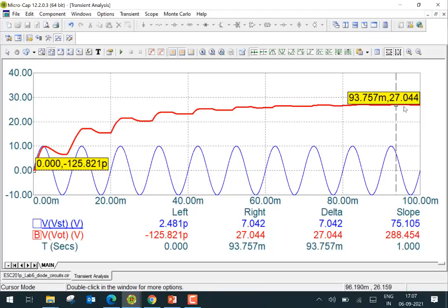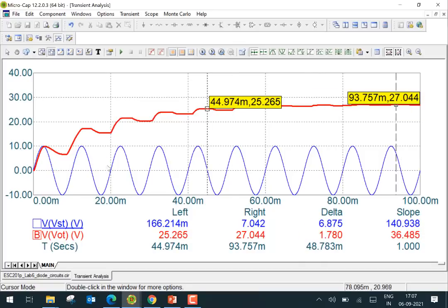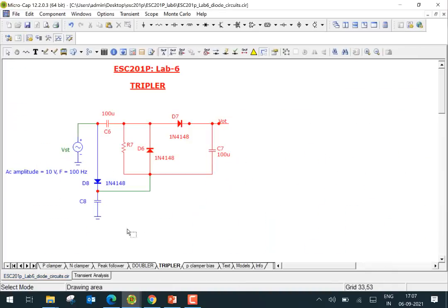30 that we expect, again, because of all the diode drops, there are several diodes in the circuit, and each one has a drop of 0.7, 0.8 volt here. Note that if we take a 0.7 volt drop, we expect at least 3 diode drops, so you can see the errors that are likely to be there in the volts range, right? So it's giving you close to the value that we want, roughly triple the value of the input sinusoidal amplitude. All right, so that is there.